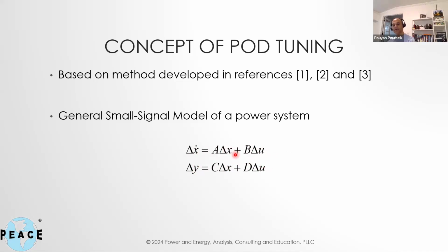So in the context of the power system, states are things like the flux dynamics of a machine, its speed, its rotor angle, or in the case of inverters, the various states of the control logic inside the converter. Like if we're talking about, in these cases, the GFMs were virtual synchronous machine GFM, so it'd be all the states associated with that virtual synchronous machine model inside the converter, plus its current and voltage and frequency regulation control loops, etc.